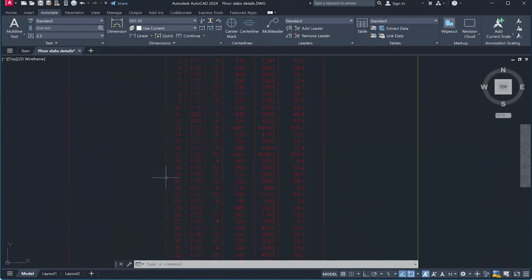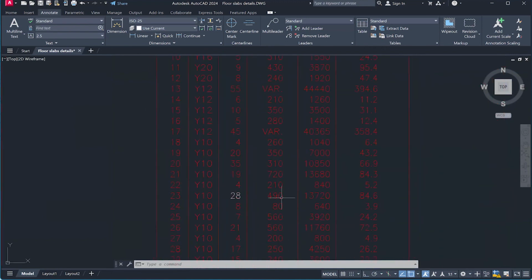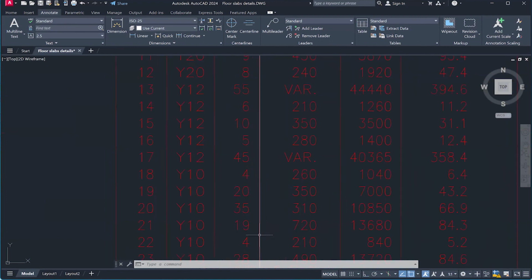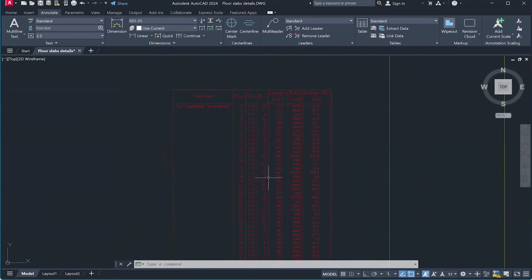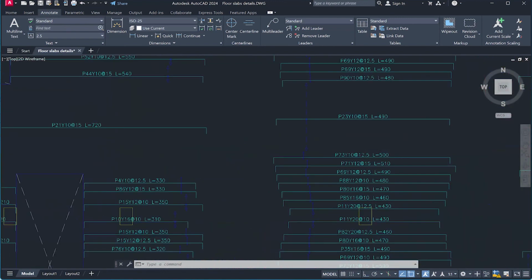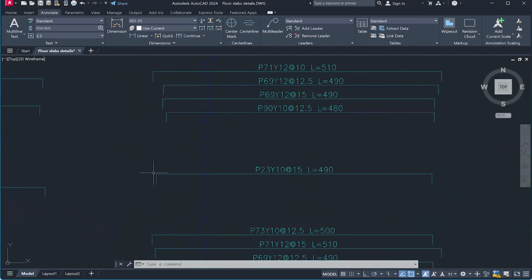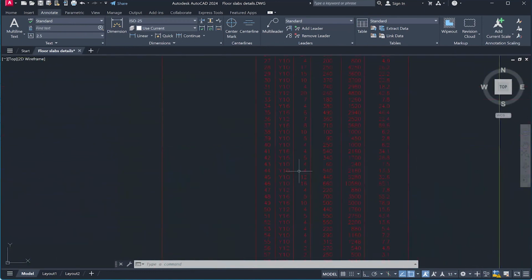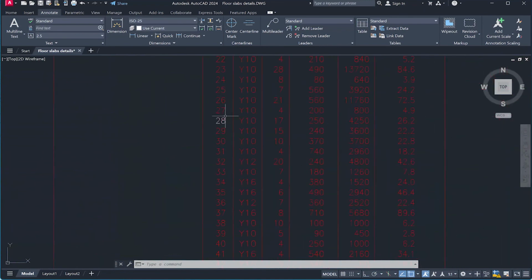Position 23, it's there, 28. Then if I add another column, I then assign next to it that it is a shape code 35. Then in terms of bending, we've already assigned the length is from there to there is 4.9 meters. Shape code 23 there. Then you've got double hook.